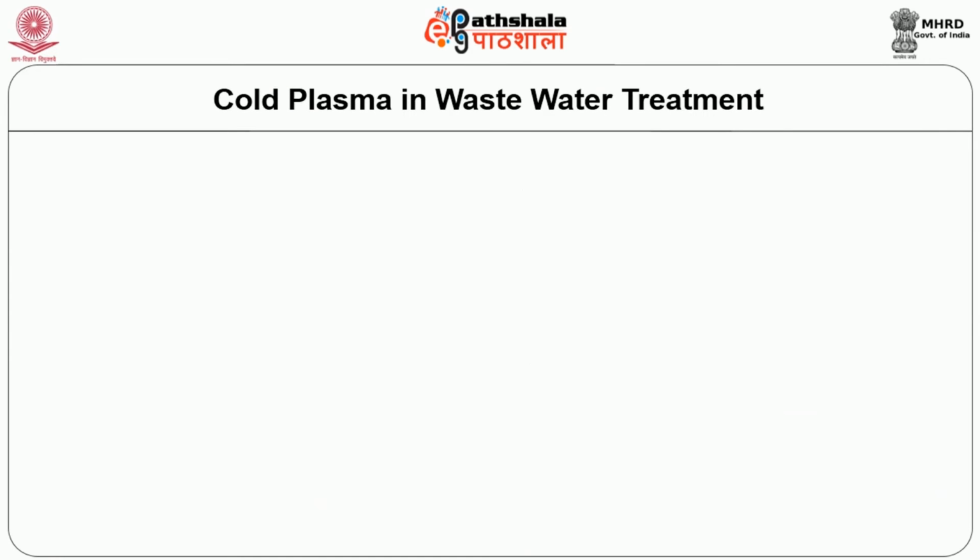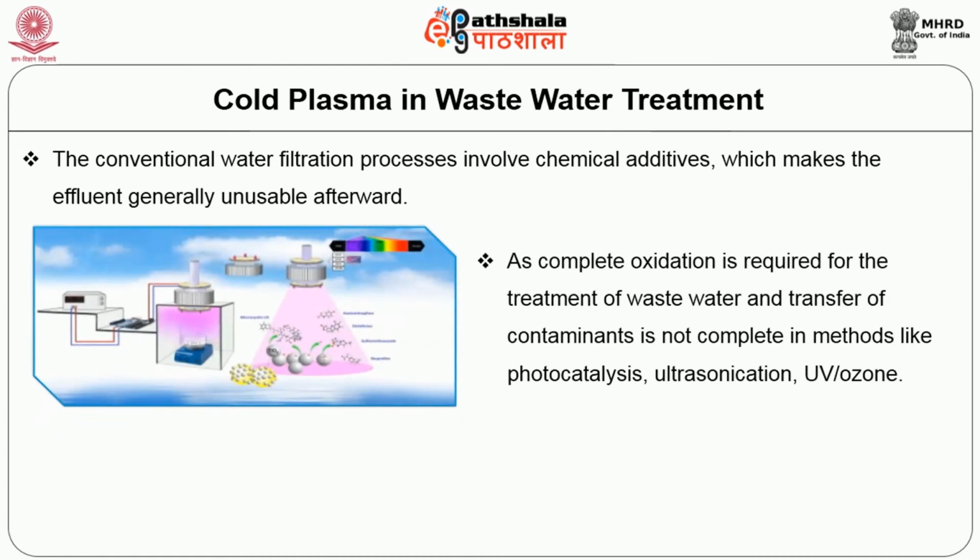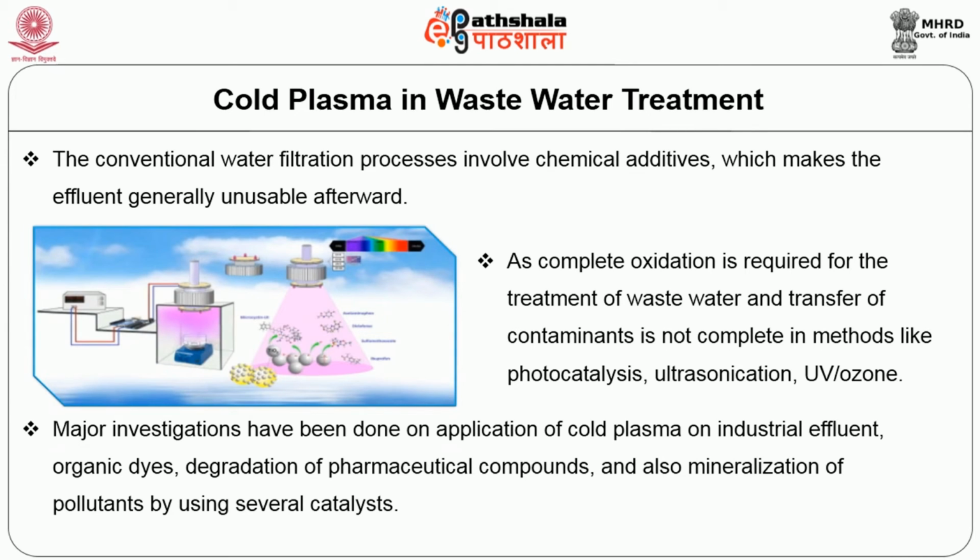Cold plasma is also used in wastewater treatment. The conventional water filtration process involves chemical additives, which makes the effluent generally unusable afterwards. Complete oxidation is required for the treatment of wastewater, and transfer of contaminants is not complete in methods like photocatalysis, ultrasonication, UV or ozone. Major investigations have been done on application of cold plasma on industrial effluent, organic dyes, degradation of pharmaceutical components, and also mineralization of pollutants by using several catalysts.